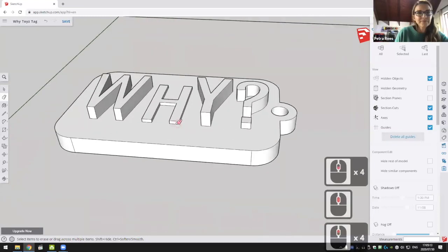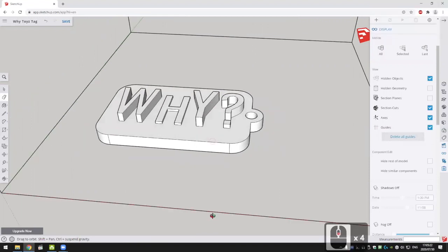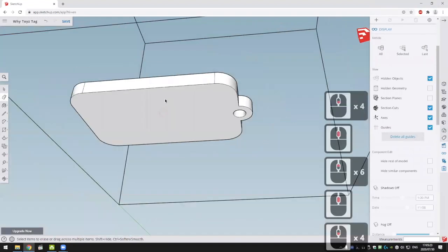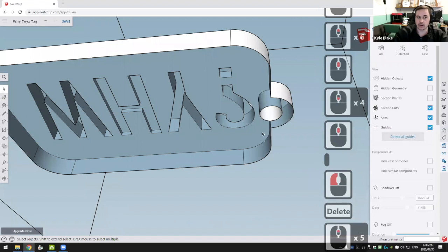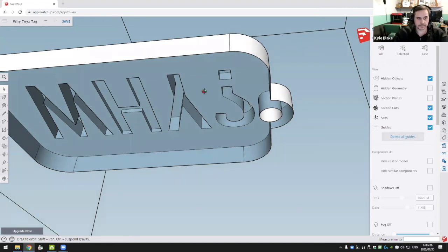And then what it tries to do with those faces is it either doubles up, or it puts those faces lower down into your print. Okay. So it's best to go and clear them up, just so that you end up with a nice hollow model like that, because then Flash Print sees it as a proper single print. Okay. So you won't end up with any problems then. Okay, thank you. No problem.